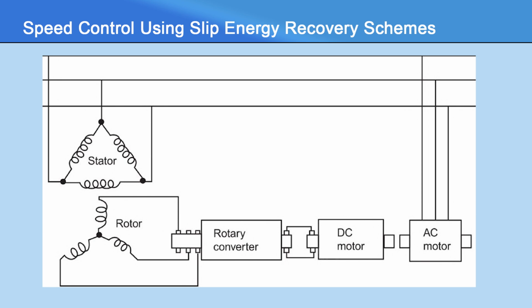which brings the rotor circuit voltage up to the corresponding value of the voltage of the supply network. The speed of the induction motor is regulated by controlling the firing angle of the inverter. The gate pulses are provided by a firing circuit synchronized with the supply frequency. Both rectifier and inverter are line commutated by the alternating EMF appearing at the slip rings and the supply network respectively.